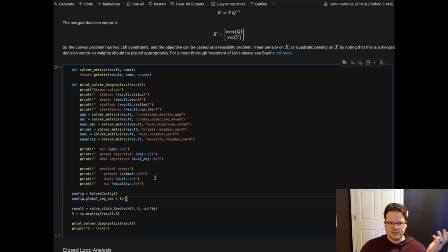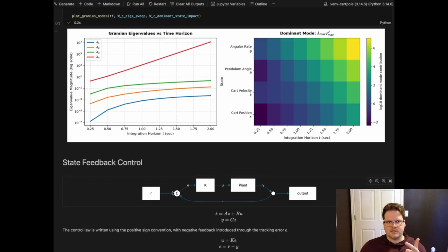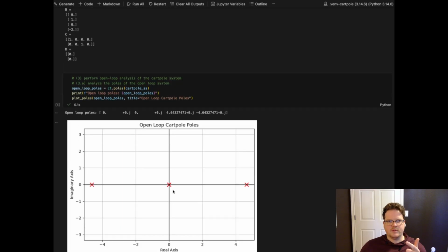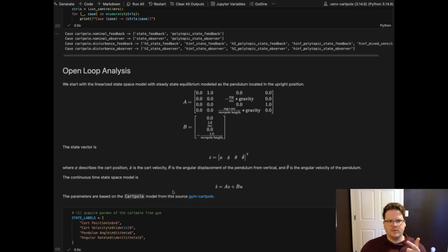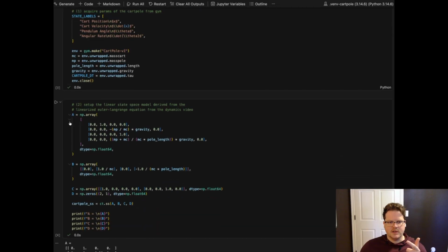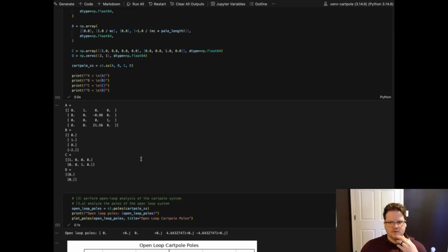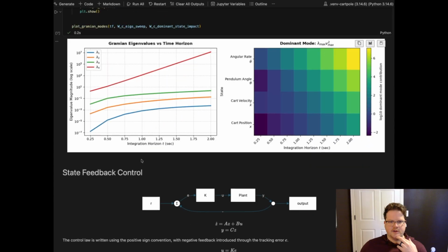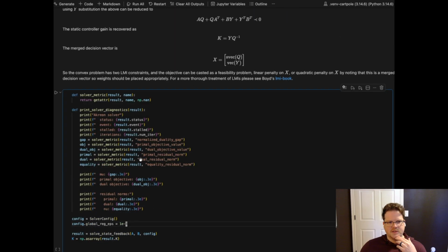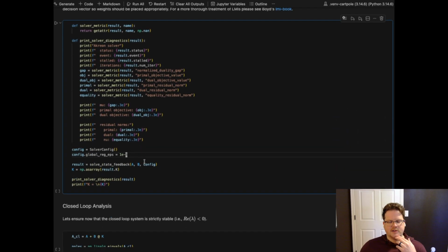And just talking out loud, it could be because it's a feasibility problem. It also could be because it's underactuated, and I didn't step through this up above, but the A matrix here is degenerate. That's not the full story, but it does add a little bit when we factor, not to get too much into the weeds, in the solution space, we get some sort of ill-conditioning. So just bump the regularization up to get more curvature, essentially.